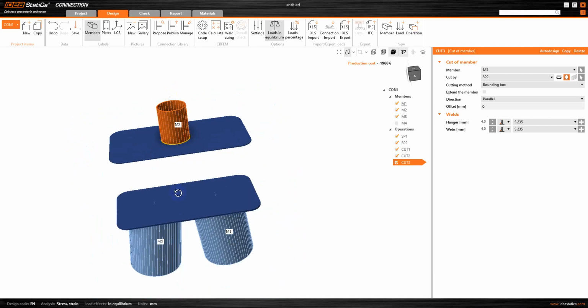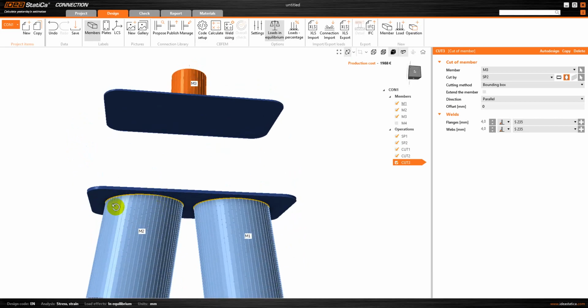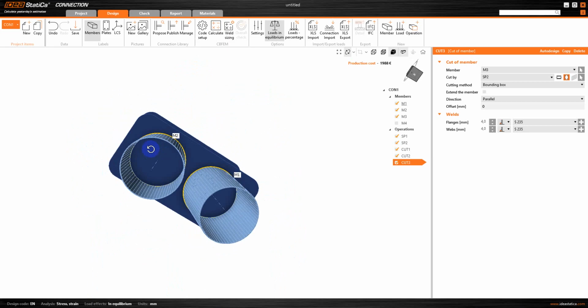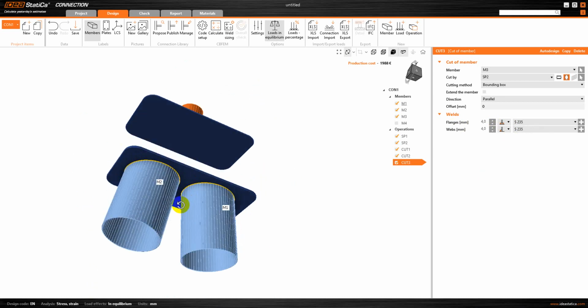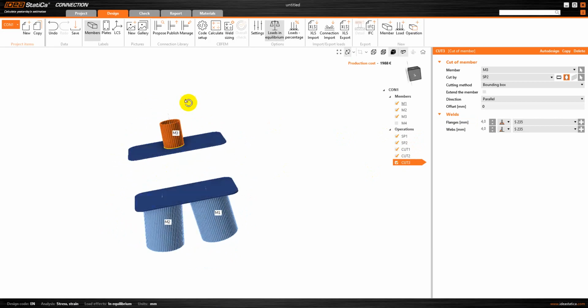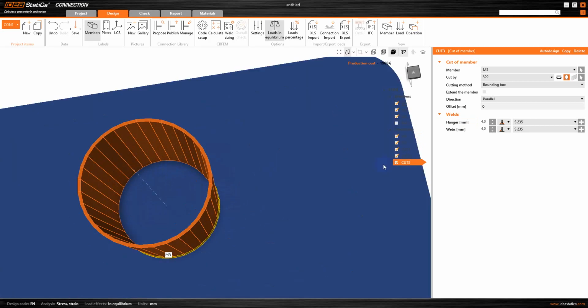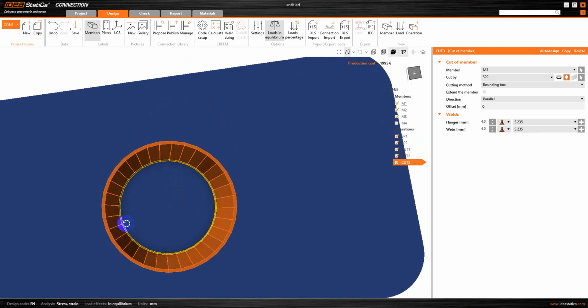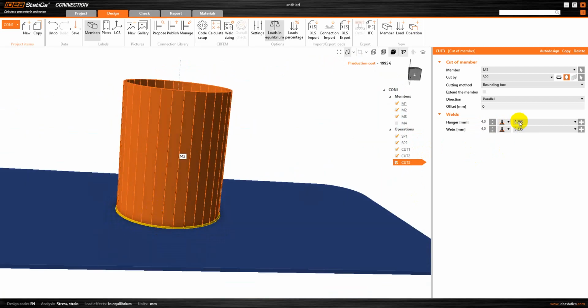And if you also want to weld in the inner side, here it is weld only on the outer side. If you want to weld on the inner side, just go here and then do double fillet weld. It has been applied on cut 3. So let us check. Sorry, on the both side. Double fillet weld. So now we can see our weld has been applied on the both side. So from here we can just adjust the weld parameter.